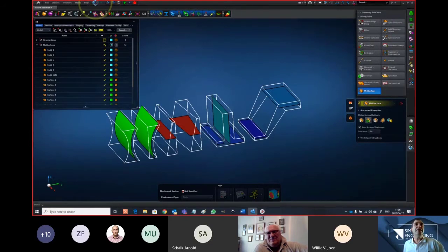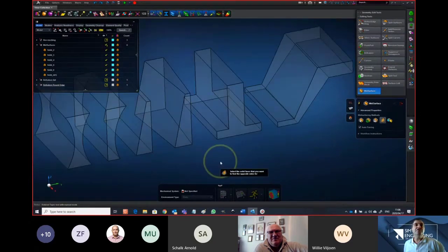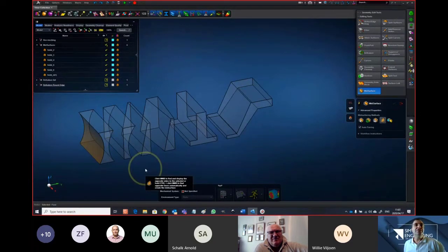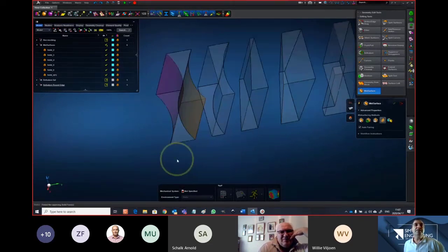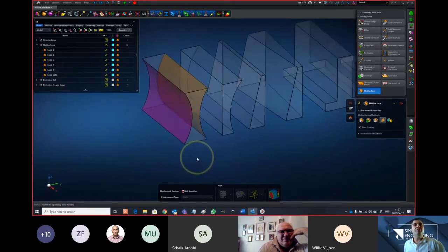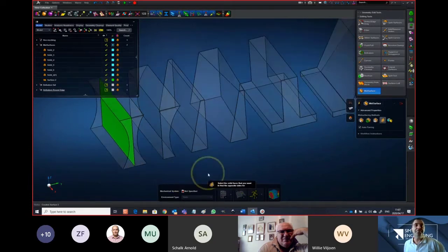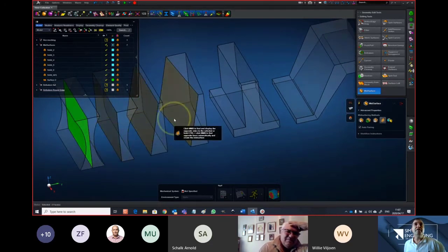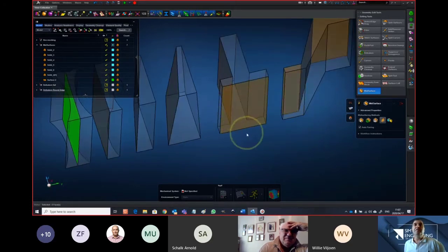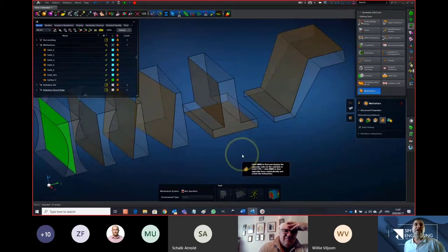So if we have a strange shape like these, the fourth option is actually the better one to choose. Here we can actually choose a face. It will, in the second step, show us the pair element or the pair face, and then if we commit to that option, it actually generates a more appropriate mid-surface than previously. So in cases like these, you would manually click all the one side faces.